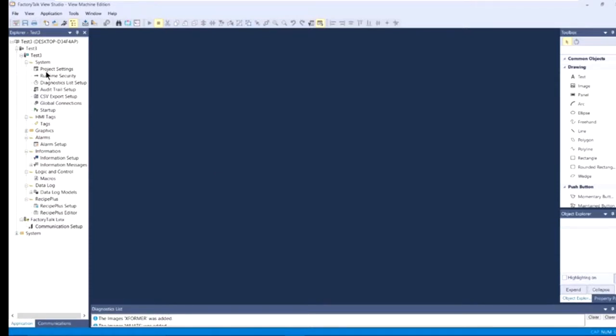Now, at that point, you'd want to go test run it and make sure that all of the graphics were lined up. They look good to me. So that's how Panel Views are converted. The conversion utility is built into the new FactoryTalk View Studio software, and it'll import all of the previous versions of Panel Views going back into the early 90s.